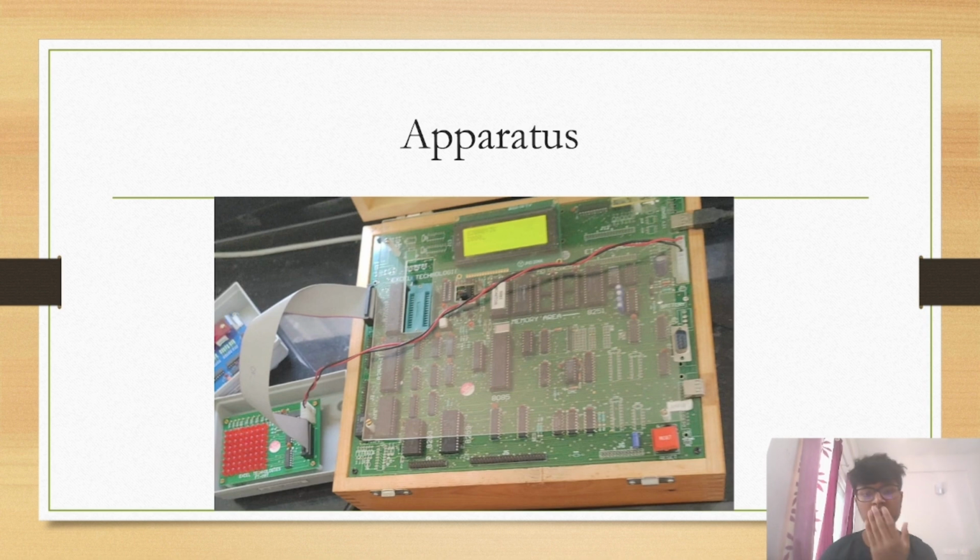Now the way this is connected to the 8085 is using a power cable which supplies power to the module, and also a 26 pin FRC cable which is responsible for all data communication from the 8085 to the LED interfacing module. So now I'll explain how the interfacing is done via the code, via the op code and the assembly code.